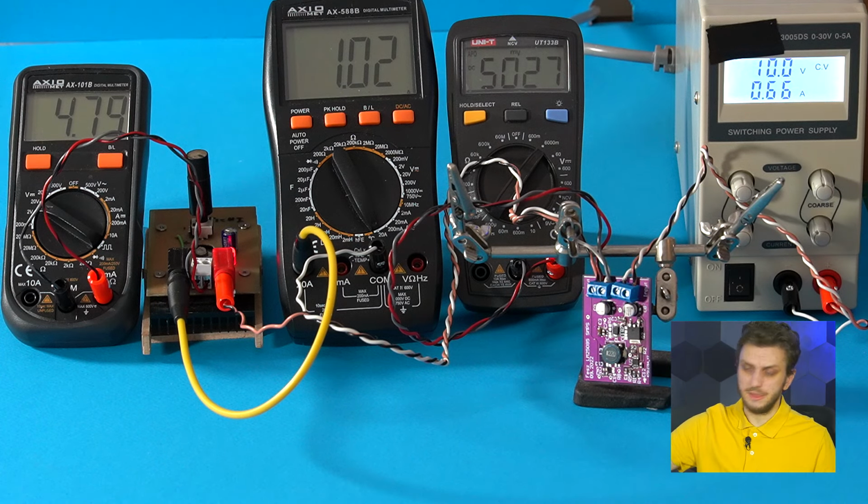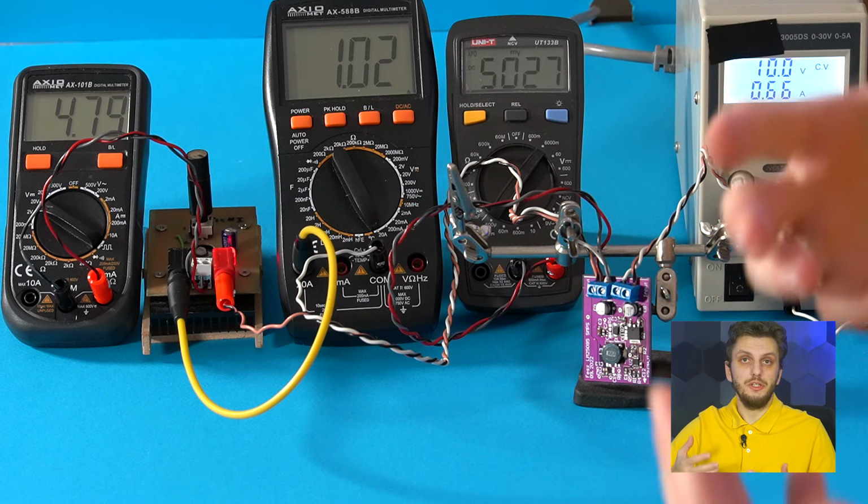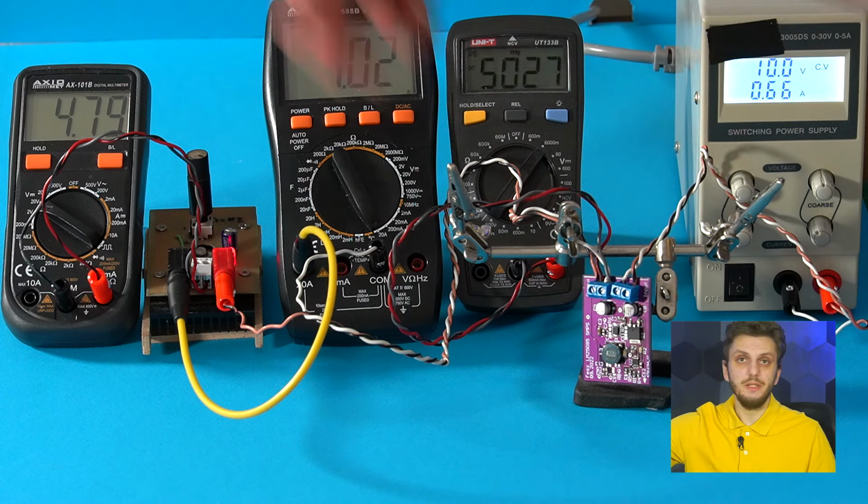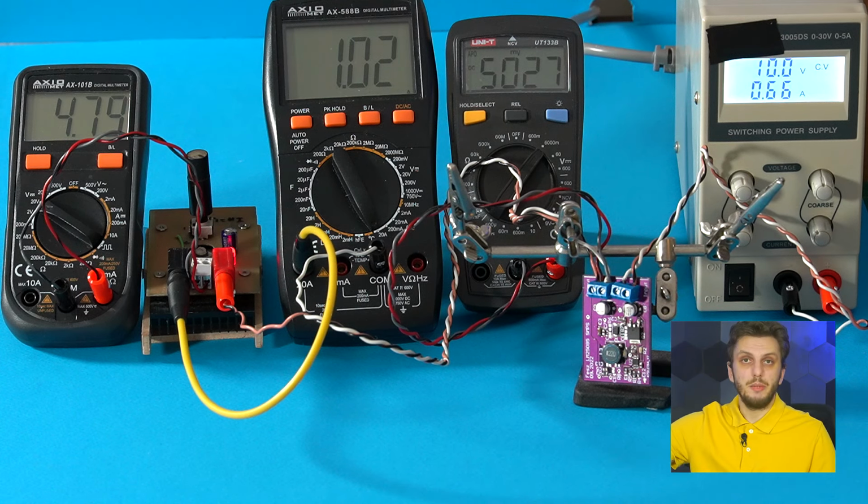Now, whether this difference is an actual problem depends on the application. So you need to know exactly what is the voltage that you need at your load at the maximum current draw. When designing the layout for a power supply, a huge impact, either positive or negative, in output voltage accuracy can be achieved based on the exact measurement or sensing point. Where is the voltage that the supply is regulating? And more importantly, where is the load that is being supplied?